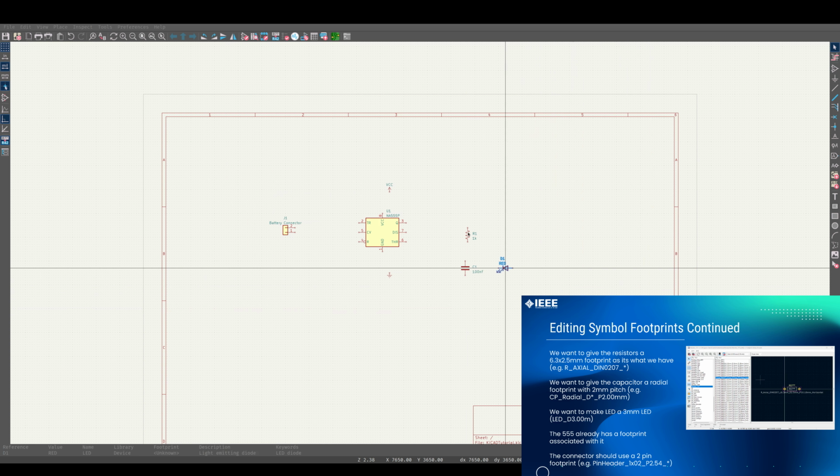Repeat the process for the LED, LED THT library, and the field would be selected. Look for anything with 3.0 millimeter. I believe there is only 1 or 2. Technically there's quite a few, but they're all the same. So anything that has D3.0 mm and only 2 pins, you're good. Clear, flat top, or horizontal, they're all the same. So I'm just going to choose the first one I see. You probably can't see that, but I've been doing it in the background there.